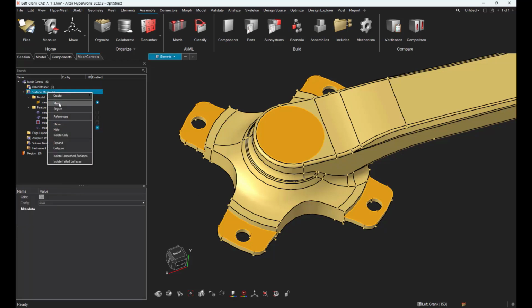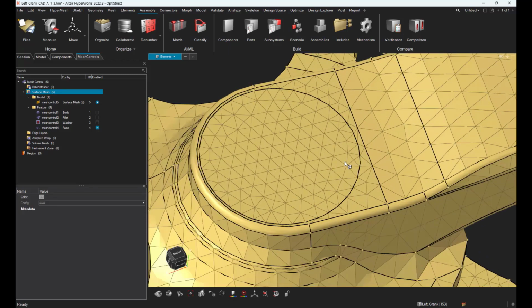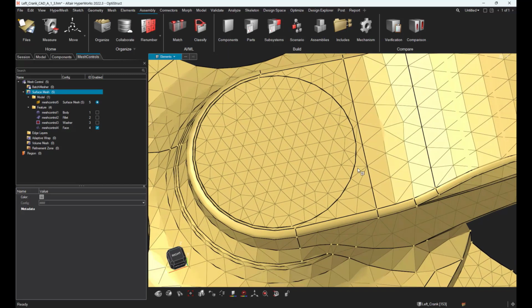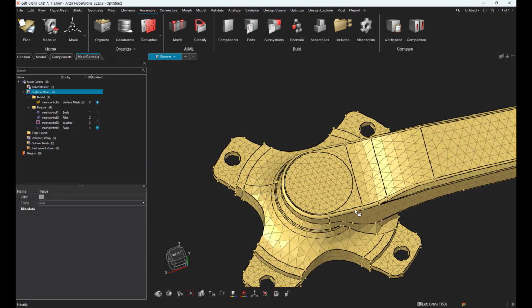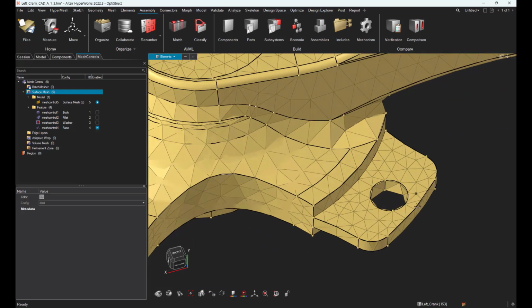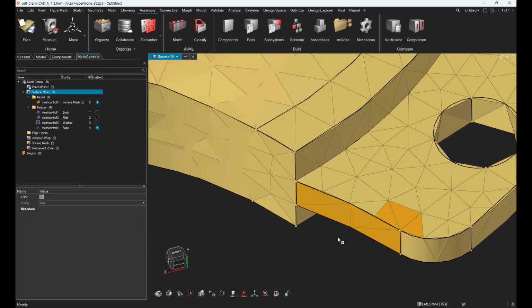If we run that, what you can get is on the top, the mesh looks to be correctly connected. No issue, no problem. But let's have a look here at the bottom. It looks okay, but if you pay attention, as you could see, we don't have a connected mesh on this location. Why?